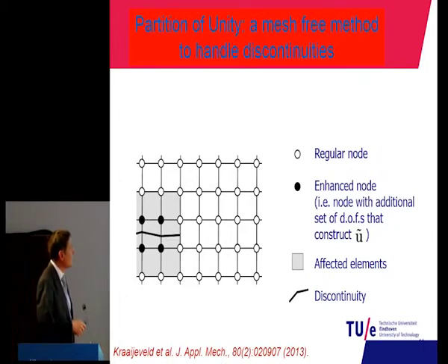Now we do mixed hybrid formulation. That means we have displacement unknown on the corners, and then we define fluxes in the style of Raviart-Thomas, and we have fluxes through the sides. We require actually those fluxes, both ionic fluxes and water fluxes, are strictly local mass conserving, so that means the flux going out of one element is equal to the flux going into the next element.